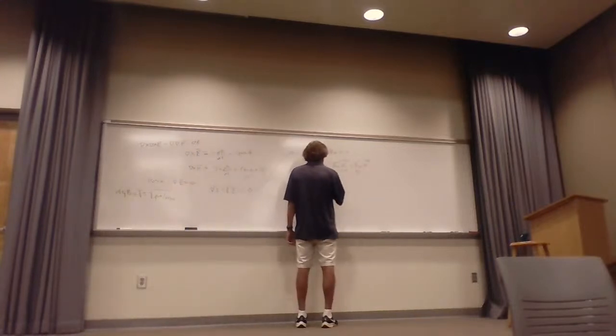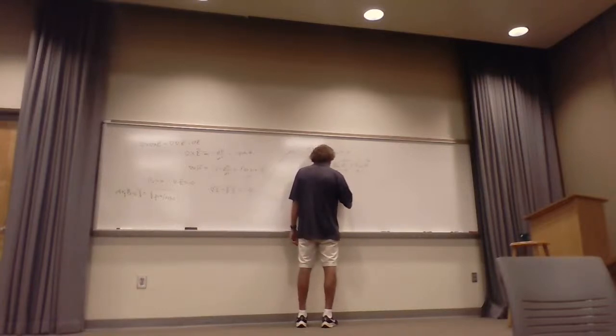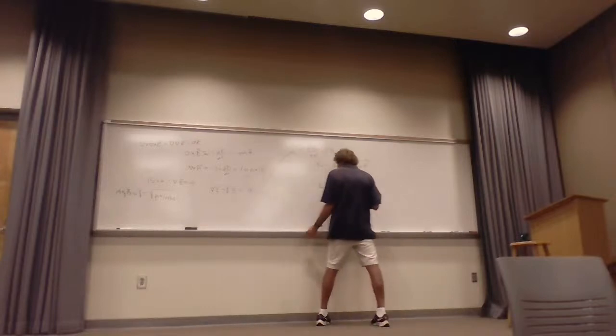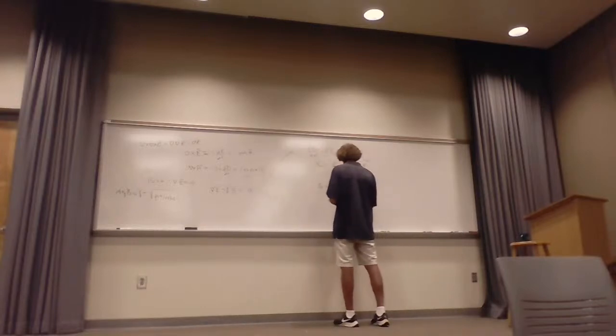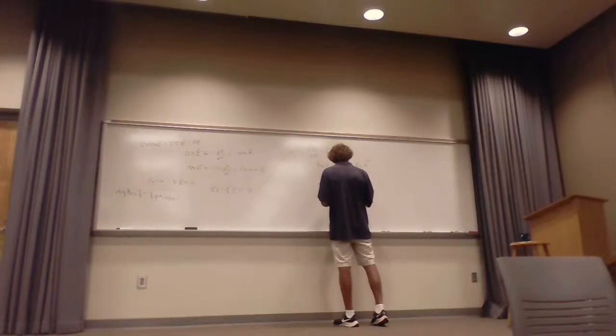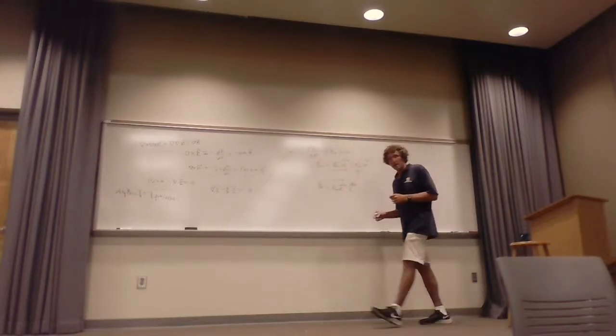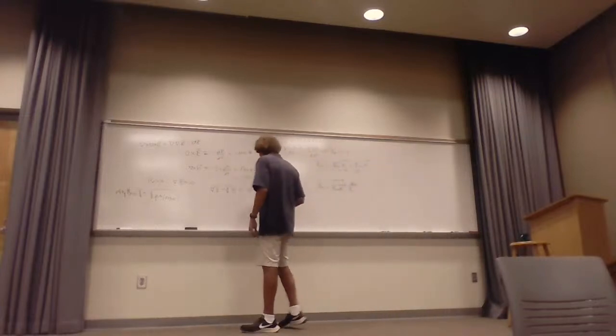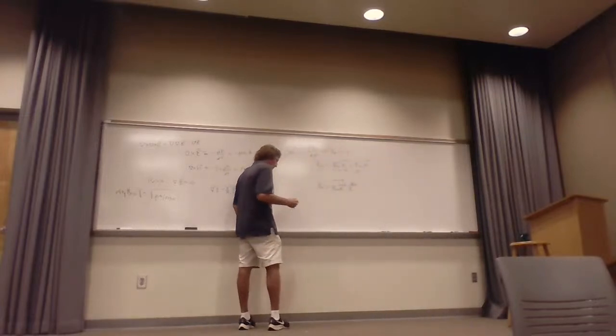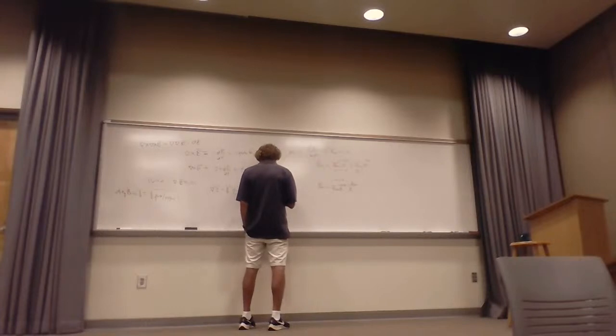So if we only worry about the right traveling wave, we have E equal to some E_x0, e to the minus alpha Z, which will give us our skin depth, times e to the minus j beta Z. There's beta, right? And we can get the phase velocity, which we found as omega over beta.